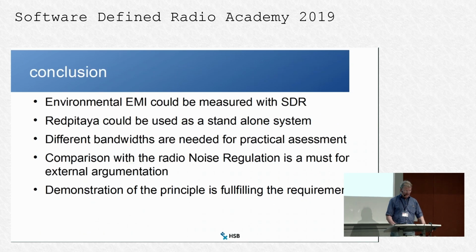I want to conclude: the environmental EMI could be measured with an SDR system. Red Pitaya could be used as a standalone system for this measurement. Different bandwidths are needed for practical assessment. Comparison with radio noise regulation is a must for external argumentation. And demonstration of the principle fulfills the requirements from the standards. So I think we have a system which could be used in the future. Thank you very much for your attention, and I'm open for questions.